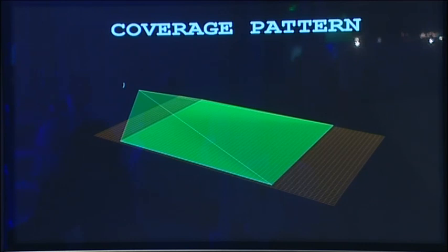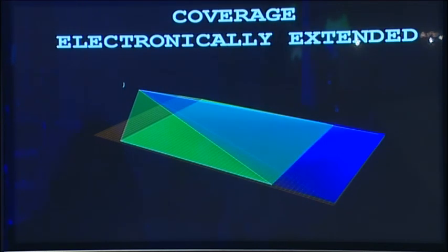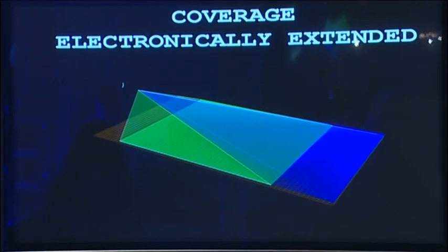So with a traditional line array system, you're out of luck there because you can't pull the system down, change your splay angles and re-rig it. You're stuck. You've got to try and persuade the audience to come and sit where you're covering. Whereas with MLA, all you need to do is put the new coverage pattern into the optimization software. It will recalculate all the DSP coefficients, and without changing any splay angles, without changing any rigging heights, you can, within a certain angle, get the MLA to broadband adjust its coverage.